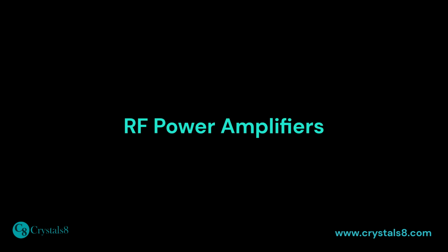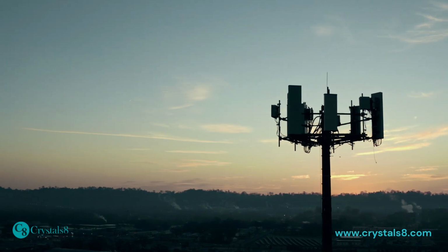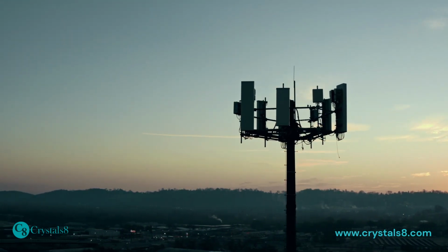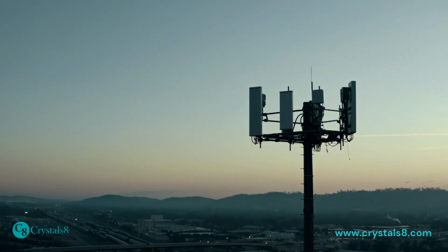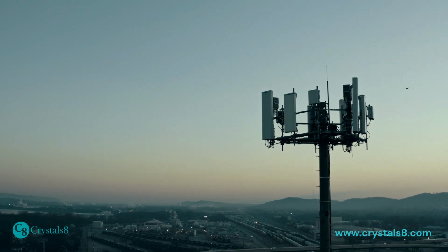Radio frequency power amplifiers. Wireless communication involves air transmitting modulated waves over long distances using antennas, and the range depends on the power of the antenna-fed signals. For wireless communications such as FM broadcasts, antennas need thousands of kW power input signals. Therefore, amplifiers are used to increase the magnitude of modulated waves to a degree high enough to travel the required distance while maintaining proper signal-to-noise ratio levels.